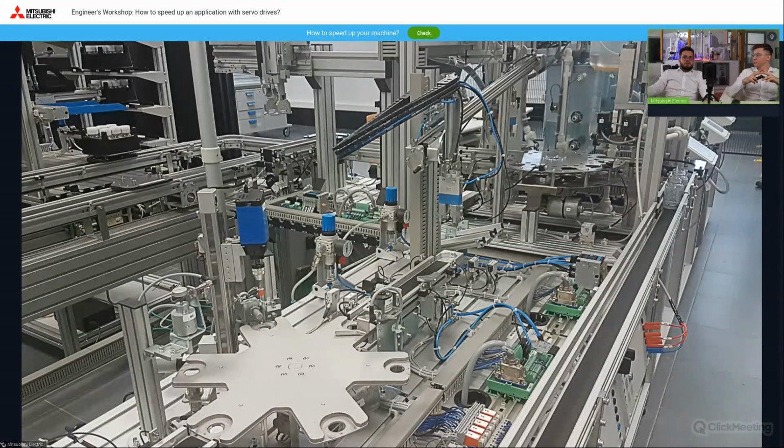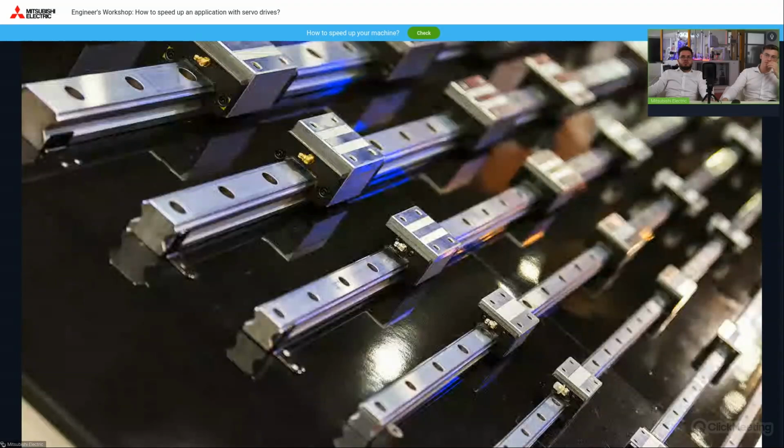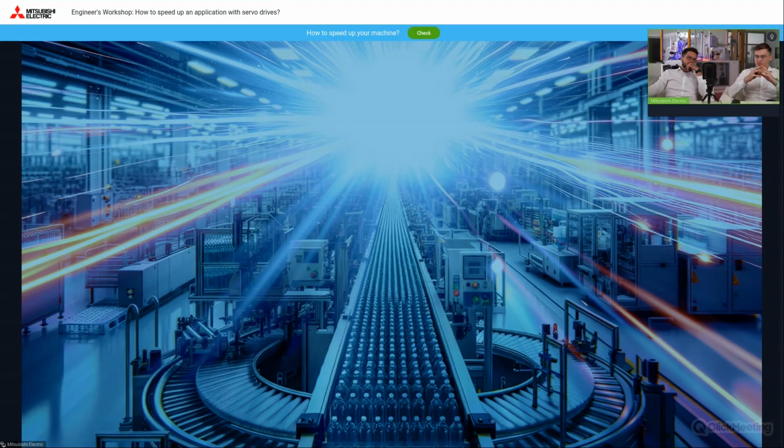Finally, the thing you need to pay attention to is the mechanical part, because we may face the situation that we are limited not by the servo, but by the capabilities of the mechanical system. Yes. In very high speed applications, often the guides are the bottleneck, because even though we don't make long runs and speed is not a problem, we are limited by acceleration. Yes, you are right.